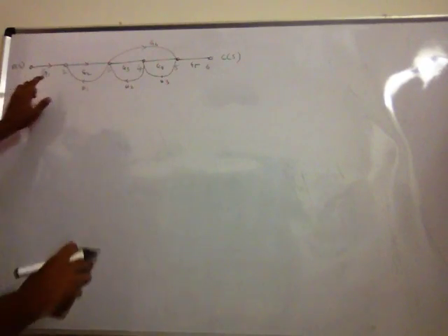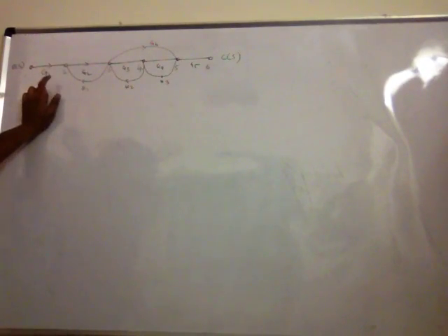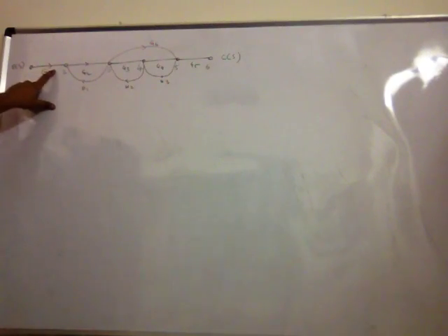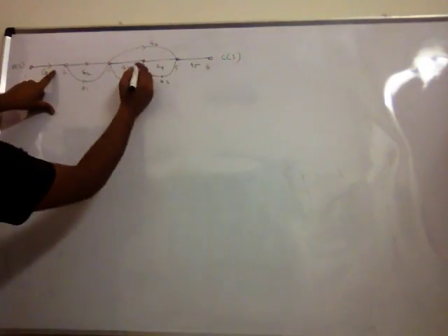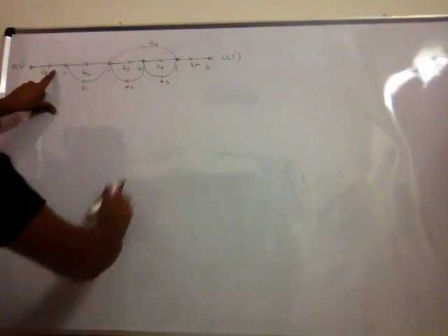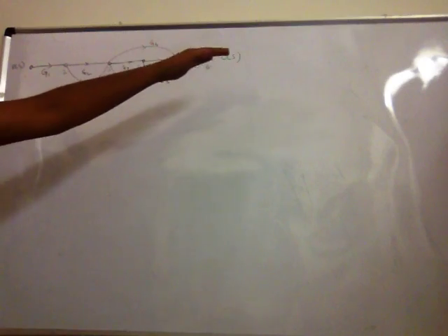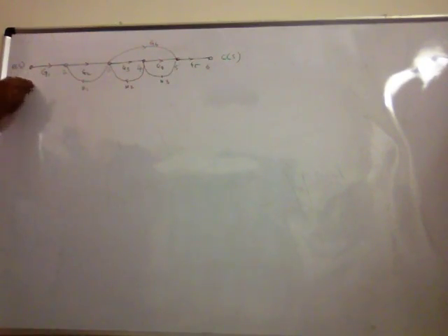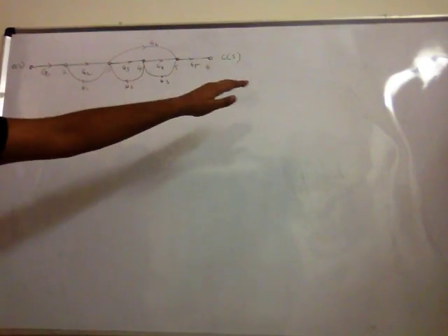Step 1 is finding out how many forward paths are in this signal flow graph. If you can see the arrow marks, how many paths are there which will take you from R of S to C of S?